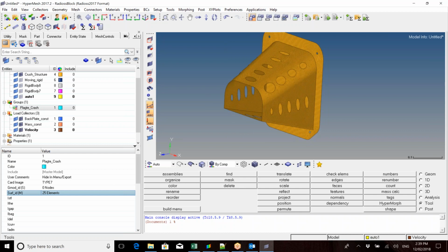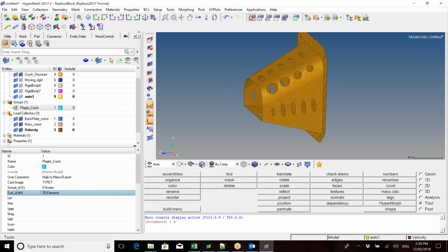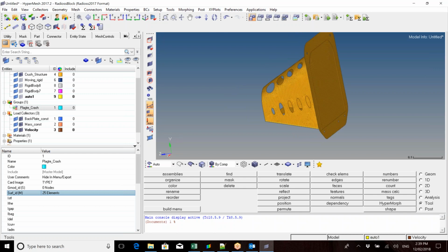What happened there was the analysis was wrong, because once it pushed through that connection, there was no more contact and the velocity didn't slow down. So what we actually saw was this front going straight out the back through this plate and just continuing on, which means that the results of that analysis were very incorrect.